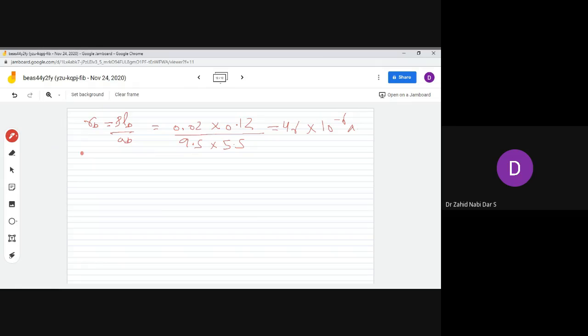Okay. Now you have to go for the I square R loss in a rotor bar. So this I square R loss is IB square RB into SR. So these things you have to take into account, and you substitute these values. Once you substitute these values, you get around 150.15 watts, because all the values you have, IB, SR, IB, you substitute there, you will get this.